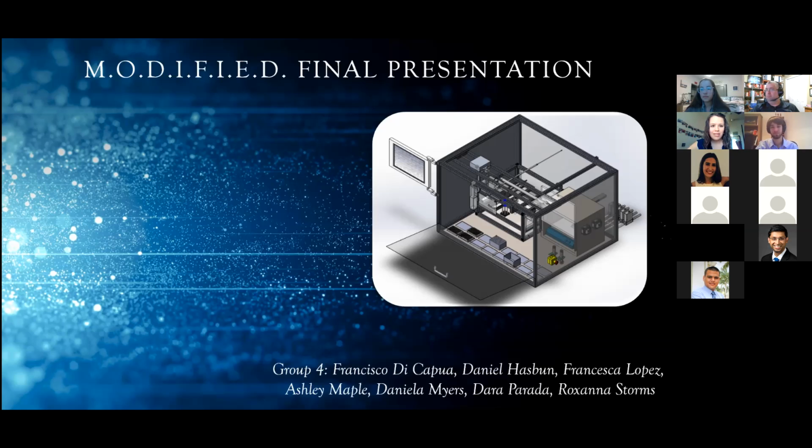Okay. Are you guys concerned about slop in the system? A big thing is that's typically why you either switch to using linear rails or you use the wheels, especially in 3D printers. You typically run into slop in your system, and that's why they tend to use grooved wheels so that you can pinch the extrusion, or you use a linear rail system in which the carriage rides on the rail.